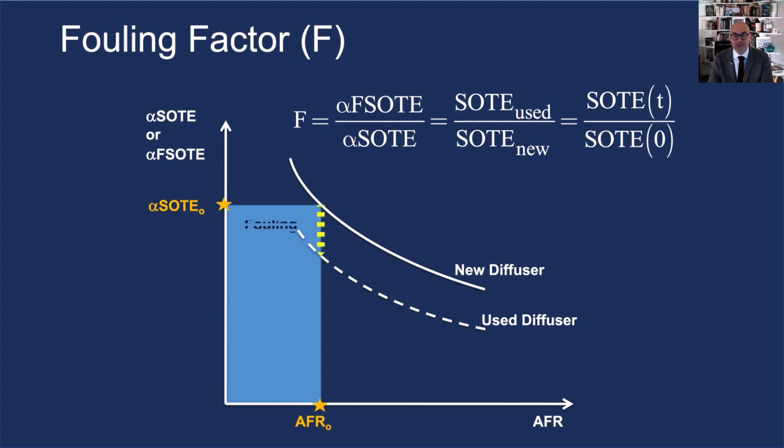Now what happens is due to fouling, this value went down, but I cannot just cut a piece of that rectangle to a lower efficiency because I have too little oxygen. So the controller that operates the aeration system and makes sure that you always meet the dissolved oxygen doesn't know anything about this. The dissolved oxygen goes down, it releases more air to compensate.